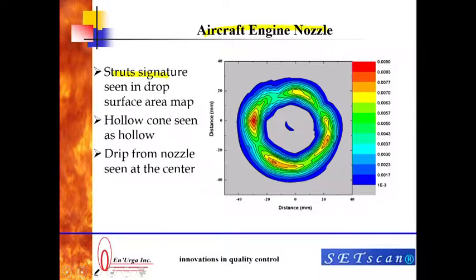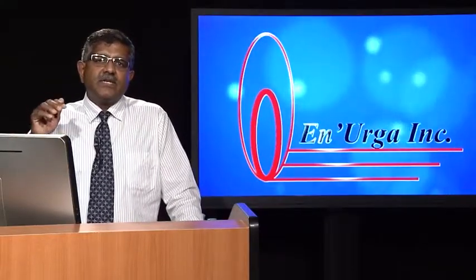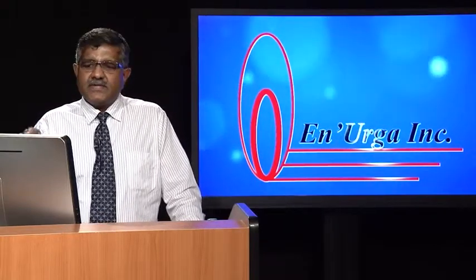The first thing you will notice is the strut signature seen in the drop surface area per unit volume. The strut means here you have very low surface area density, here very low surface area density, here very low surface area density, and here very low surface area density. So, that shows you have 4 struts that are holding the nozzle up. Once the manufacturer saw this particular example, they recessed the struts further into the nozzle body, so that they could get a much more uniform contour of the surface area density.